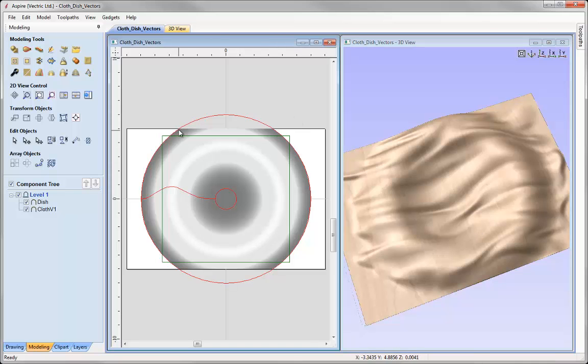Now again, I've deliberately positioned this so that the shape is coming down to 0 in the corners so that I can ensure that the dish has got 4 points that it'll be able to sit on. I've also tried to make sure that I've got a low point in the middle here, so even if it sags a little, because remember this is going to be very thin material, it'll also pick up that center point to sit on as well. So there's a little bit of thought gone into some of the depths around the model at this point in time.